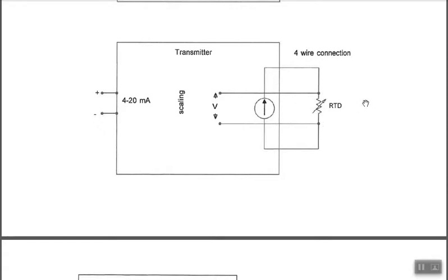And if you step back and look at this 4-wire RTD, it's important that you see the simplicity of it. Essentially, if you just look at the raw RTD, let's say you just buy an RTD, you get it shipped to you, you open the box, and it would have 1, 2, 3, 4 wires. It's important right away that you understand that 2 of the wires are identical, and another 2 wires are identical. So always keep that simplicity in mind.